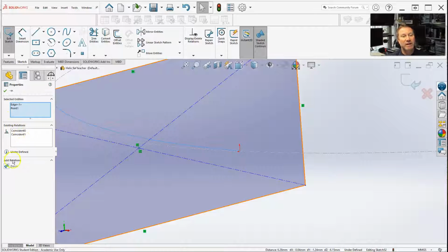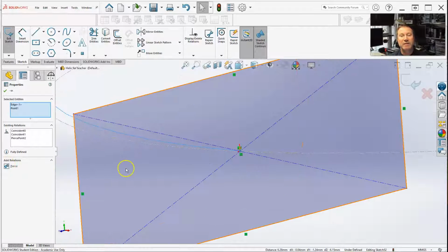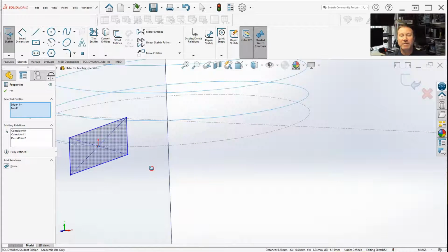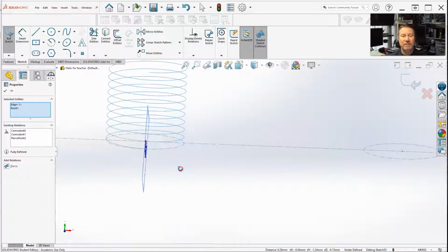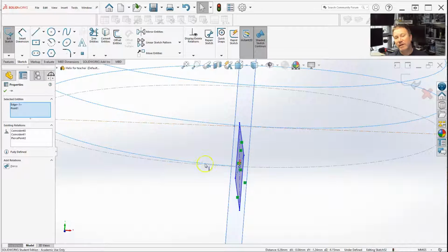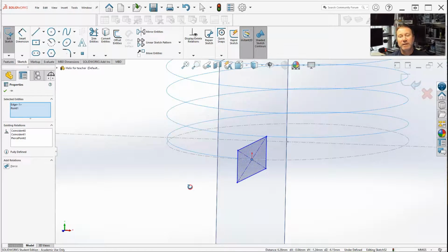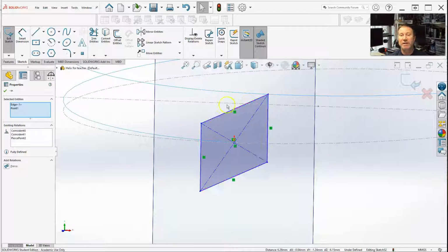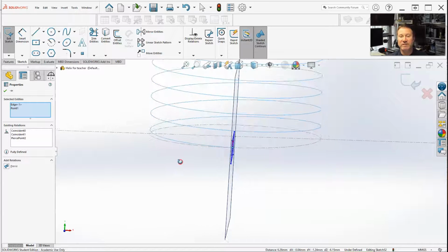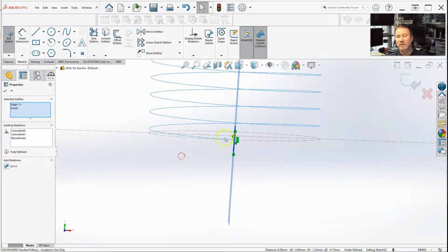Right now, they're not. The concept here is you've got to hit the pierce button. The pierce button will actually push this straight to the end of the helical coil, right in the middle. So that's one of your constraints. Whenever you create a sketch, you can create it anywhere on this plane. So now the sketch is, like I say, perpendicular to the actual helical coil right at that point.